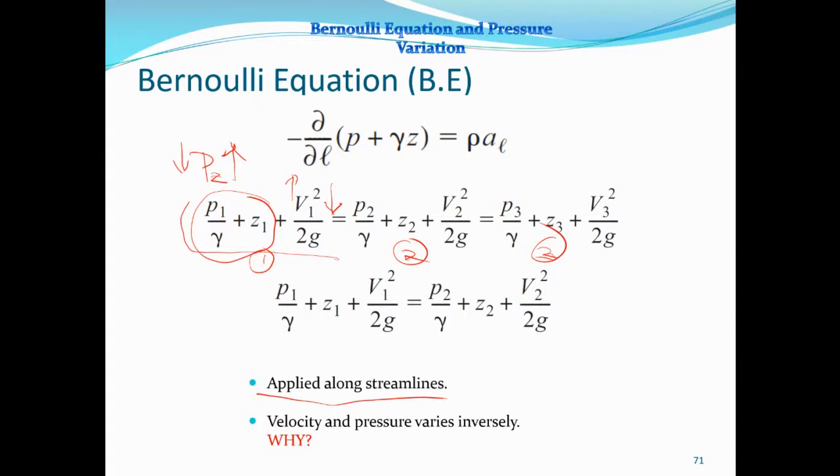We are going to do this practically in water engineering, CE 335, when simulating flows in fluids. We are going to see how to measure the velocity using a pitot tube, which is the next part we are going to explain. We will see this variation of velocity with pressure: when the velocity increases, the pressure has to drop, and when the pressure increases, the velocity has to drop.